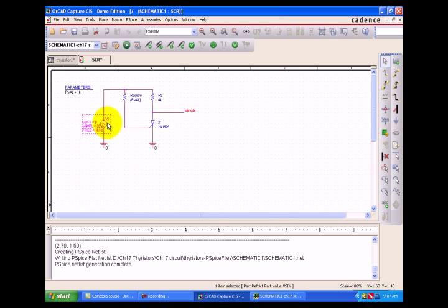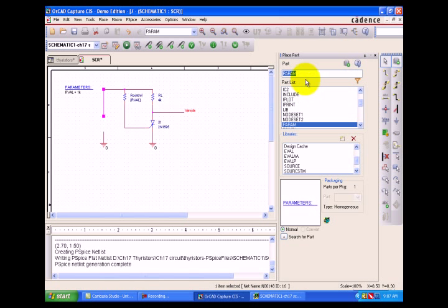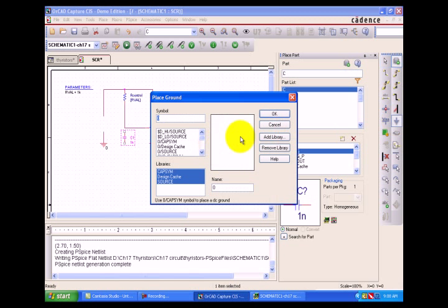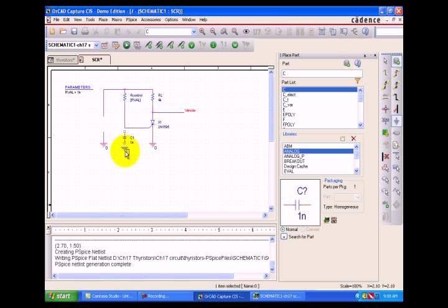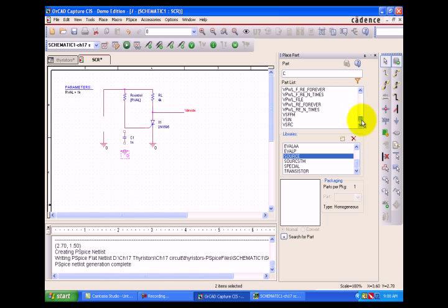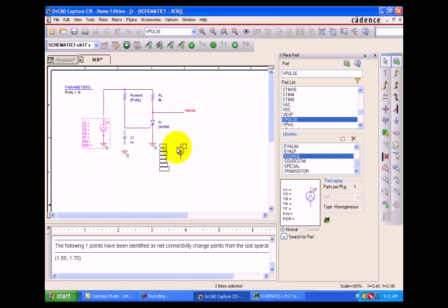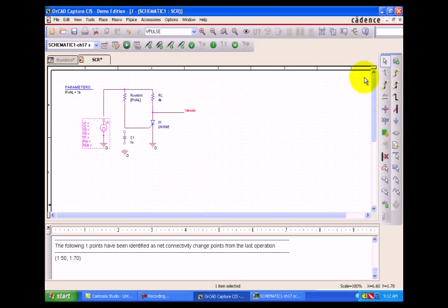Change the value. Now we're going to change this to a square wave. So give the input a square wave and simply add capacitance. Now we will use a capacitance to vary the turn-on time and the turn-on delay time. So this is the capacitance and the input will be the square wave. We can give the square wave input towards the schematic.